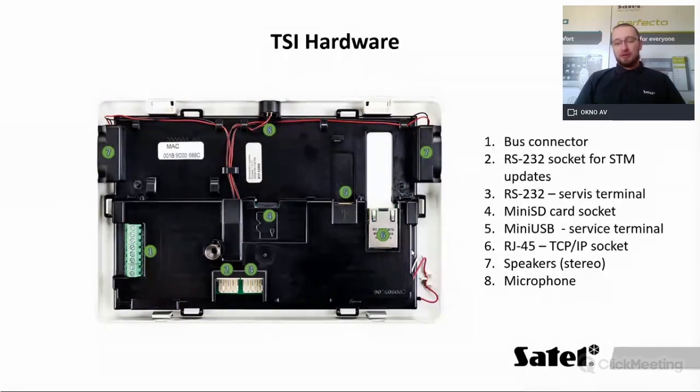Please remember about the power supply. This is quite an amp-hungry device. It can take even 600 milliamperes, so please take into consideration putting in a proper power supply for it, especially if you are using smaller Integra panels. But also please remember, if you put a keypad at a longer distance, to use thicker cables, because 12 volts going through a 0.5 millimeter wire is not exactly the best for it, at least for long range.